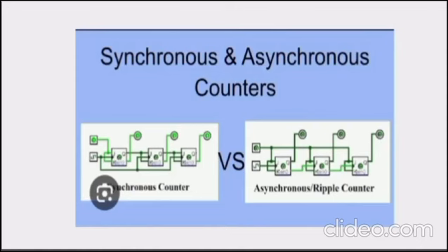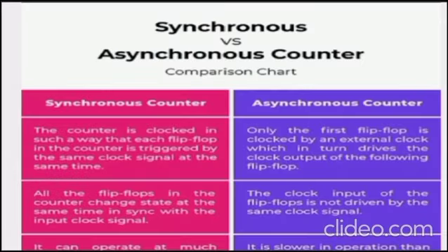The picture is synchronous and asynchronous counters circuit. Synchronous and asynchronous counter comparison chart. Synchronous counter: the counter is clocked in such a way that each flip-flop in the counter is triggered by the same clock signal at the same time.